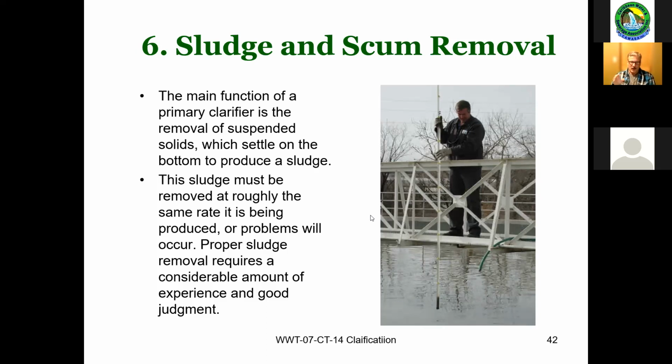You can see the amount of sludge being withdrawn. You can see how long your valves actually stay open, because you only need to remove sludge through a hopper when there's sludge present. So we adjust those timers accordingly. They might go 5-minute run time per hopper, and at different times of year they might go to 7 minutes, because we're trying to remove the sludge without removing too much of the primary water itself.